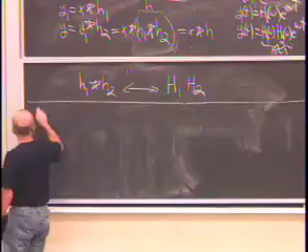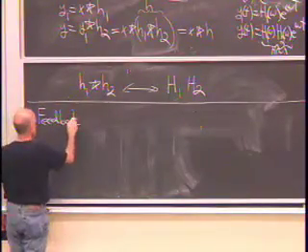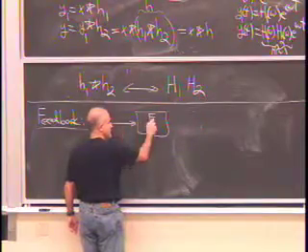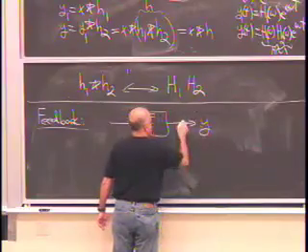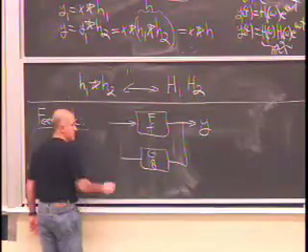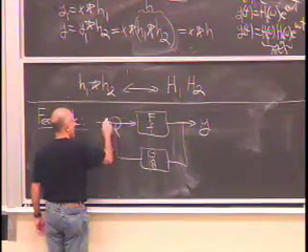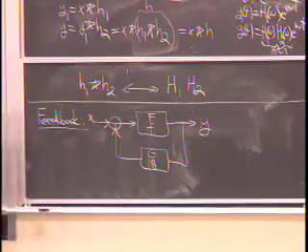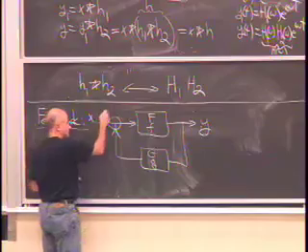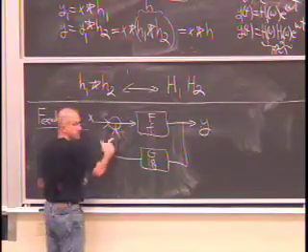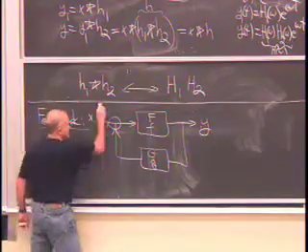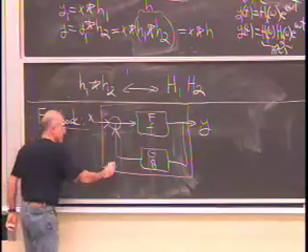Now we get to feedback. So here I have a system F with frequency response F and impulse response small f. I take Y, I send it through another LTI system, G, and I mix it with the input signal. Now you've got to be careful. Very often these will have opposite signs, and if they do, they'll be specified on the diagram. So I may say this is plus, this is minus. But if I don't put anything, like I'm about to do now, you assume both of them are plus. So this is your overall system. Call H. Okay?